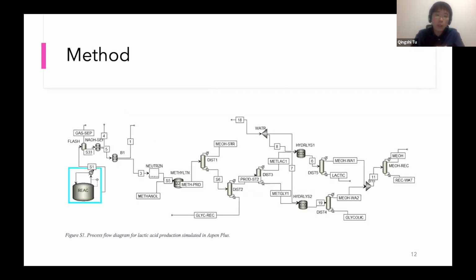And then what we really want to know is if we scale up this technology, is there any place where we can, say, save some energy, right? Because in the lab, you don't account for, let's say, heat recovery and all that. So what we did is we used SM+ to simulate the reaction itself, as well as the separation of co-products, the purification, and then you get the lactic acid and recycle the glycerol, and the heat integration through pinch analysis to actually reduce the utility use and all that.